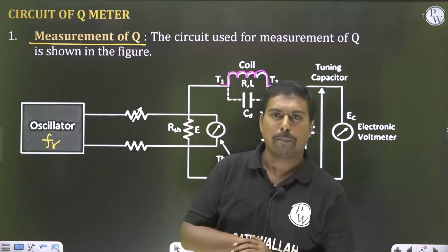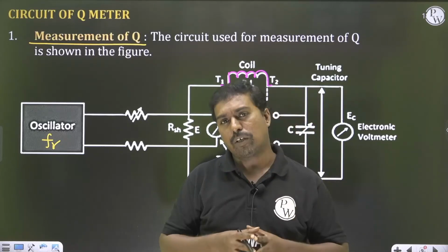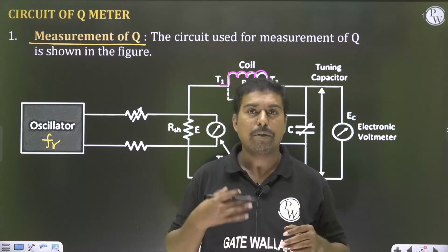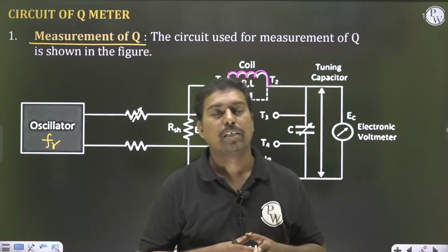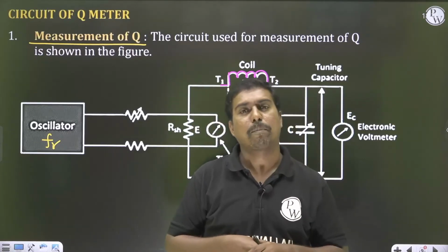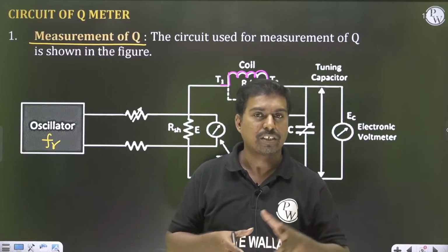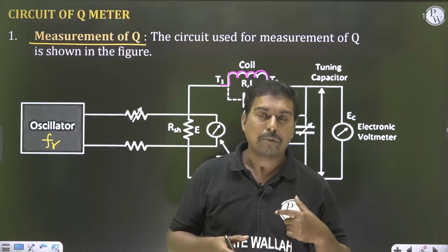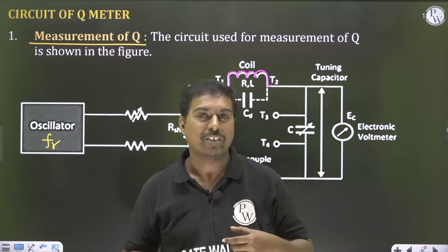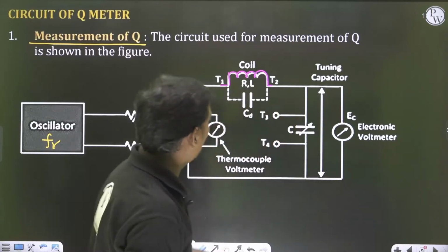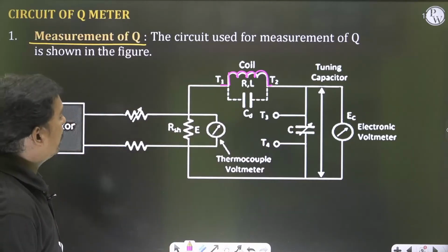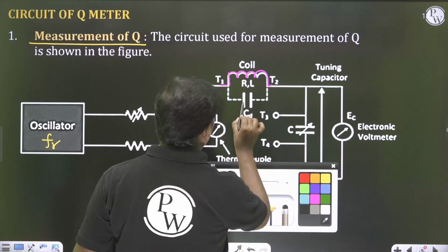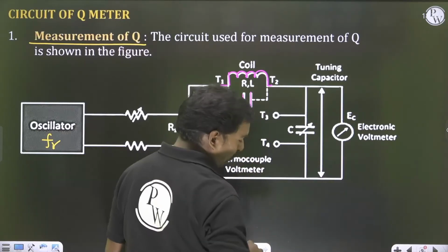That is called distributed capacitance. In simple words, no resistor is purely a resistor, it may have some inductance and capacitance effect. No capacitor is purely a capacitor, it may have some inductance and resistance effect. Vice versa, an inductor is also not a pure inductor, it may have some resistance and capacitance effect. So these are the distributed capacitances, and this parameter we also have.